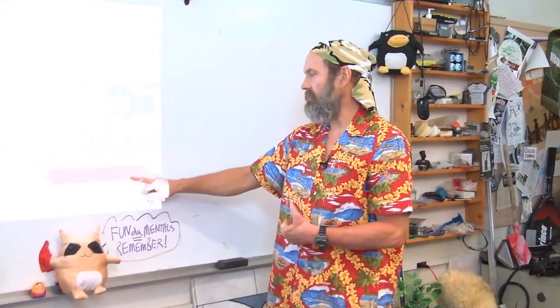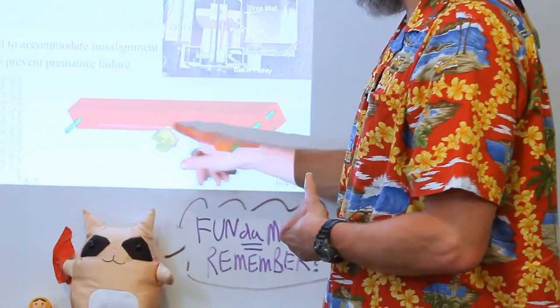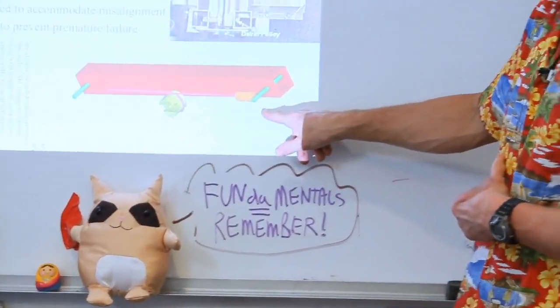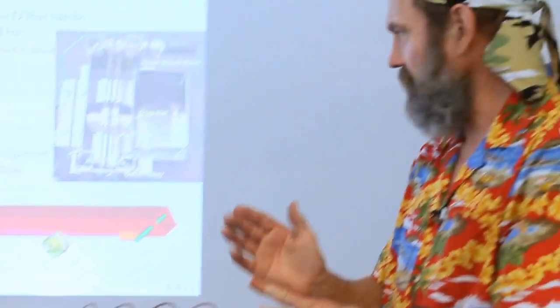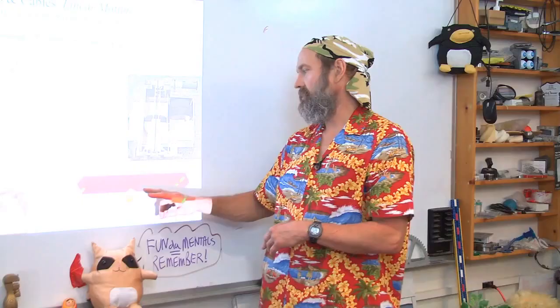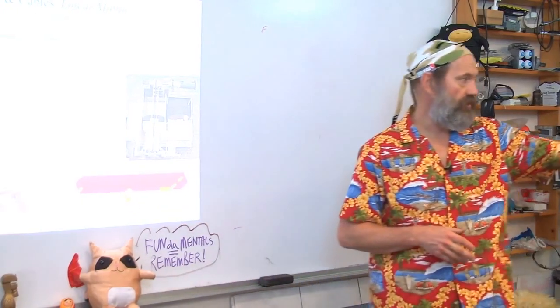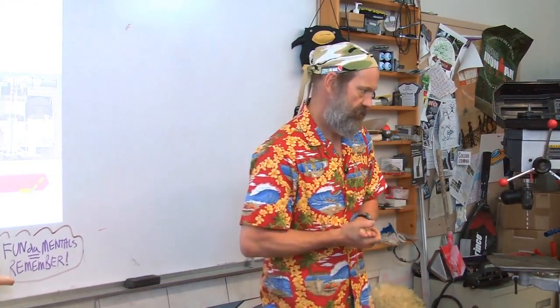Be very, very careful. You sometimes will say, well, I'm going to get rid of the problem of using a belt by using a cable because it's not so sensitive to misalignment. Yes, it is still sensitive at the end. You can use the capstan effect to give you the friction you want, or you can use a bead belt, which is not very sensitive to alignment. There are a lot of options in your toolkit.